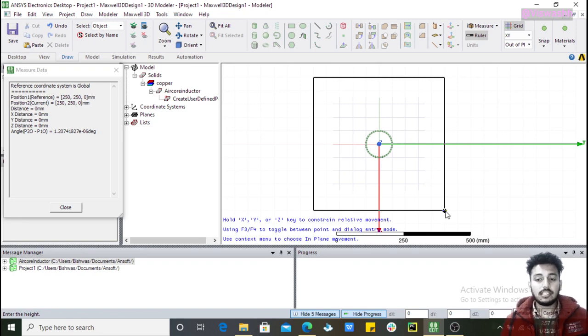Now, when you move the mouse, the measurement is not precise. To do a precise measurement, you press the Tab button on your keyboard. The first time it goes to dx, that is to change the x-axis, so you need to specify it. With the second Tab you go to y, and with the third Tab you go to z. And as I already said, we are on the XY axes, and we have already assigned the x values and y values.